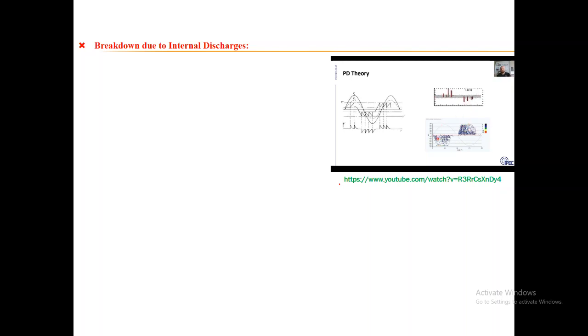Now, of course, this one here on the bottom right hand side is a condensed PRPD, which is quite common as well. It's one power cycle on top of another, so it's quite common of instrumentation to have that functionality. So instead of looking at a single power cycle where there may only be one PD, what you want to do is record data over a period of time, put them all together so that you can see this sort of pattern in the power cycle.